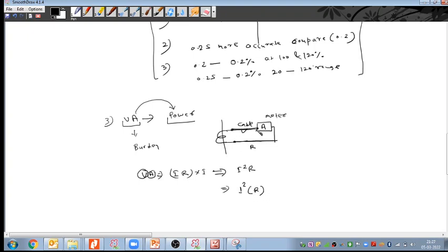So this current flows in one direction, and now it is coming back in the reverse direction. So again we need to add I square into R, which gives I square into 2RL, meaning it is going and coming back to the CT. So I square into 2RL is the required power, or required burden, of this cable, plus the instrument we are connecting on the CT. So we have to take this instrument burden.